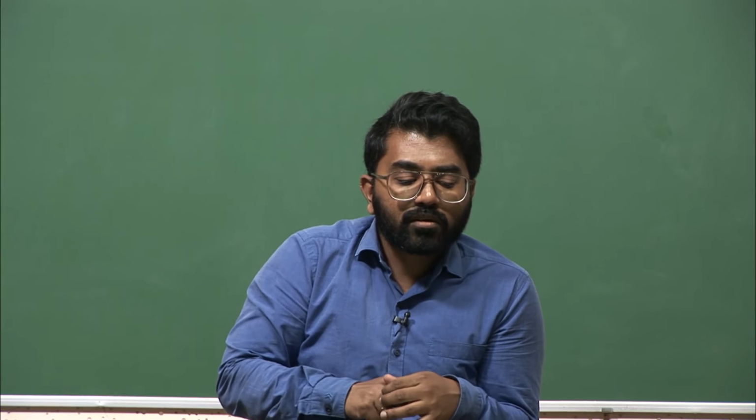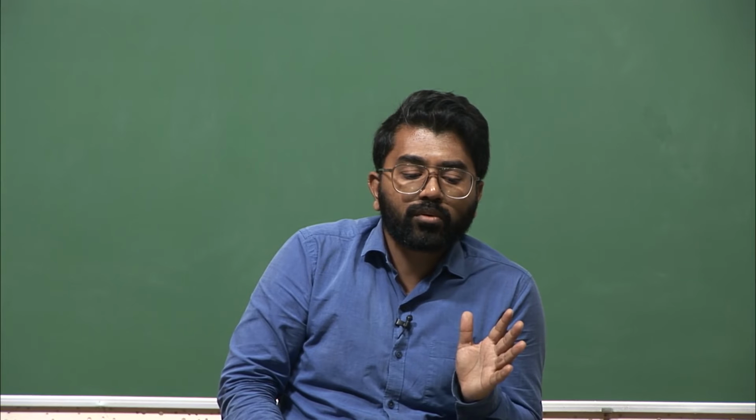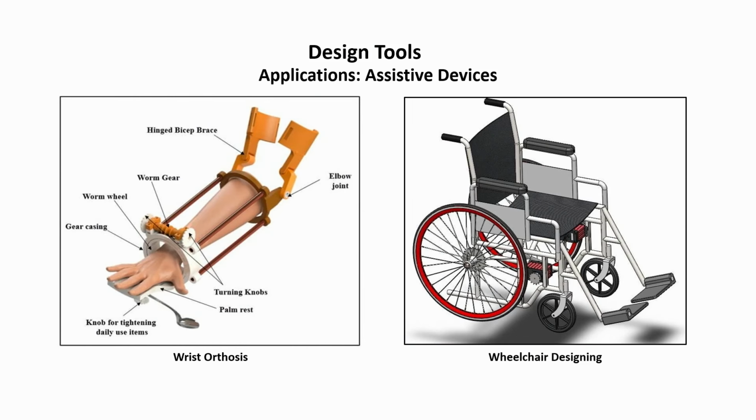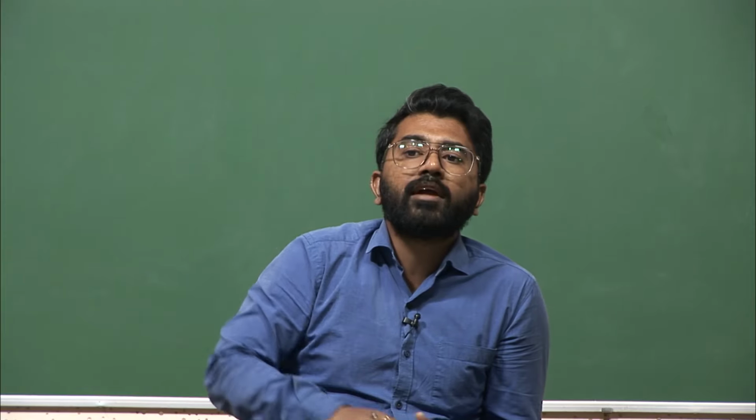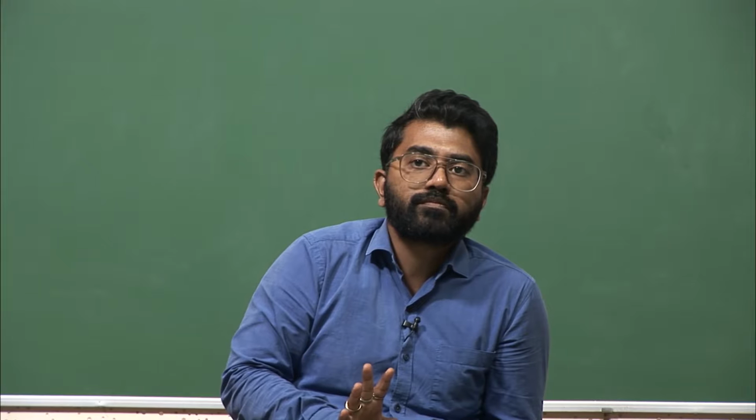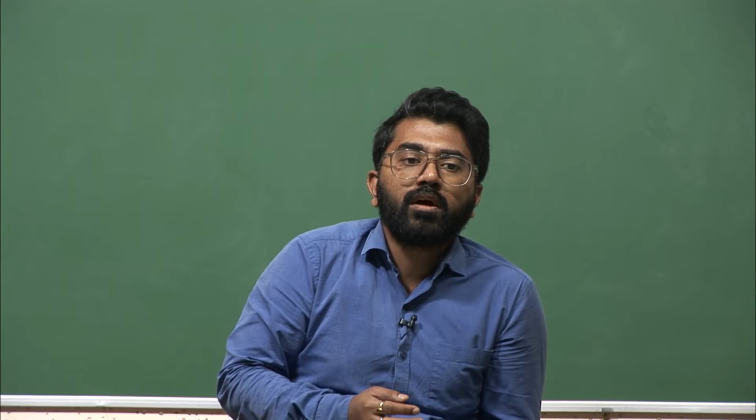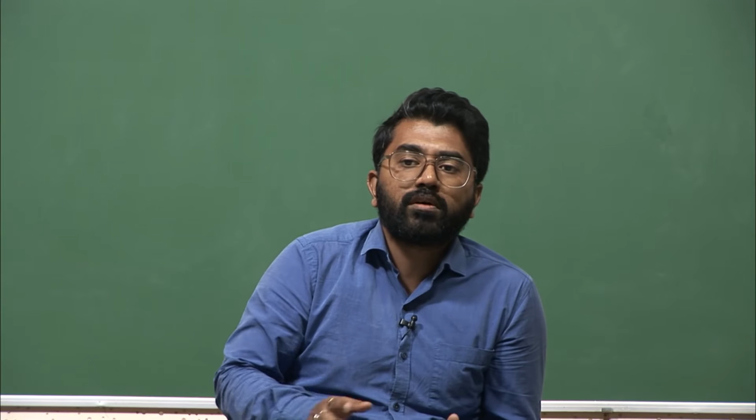So this is another wrist orthosis totally developed on SolidWorks. All the dimensions were captured from the basic human body. Typically when we are trying to make a device like a prosthetic, orthotic or a wearable device for a generic population, we would like to see the 95 percentile human dimensions or 90 percentile human dimensions. What that means is these dimensions will suffice for 95% of the human population, irrespective of their weight, height or whatever. So it's like a one size fits all kind of system, right?